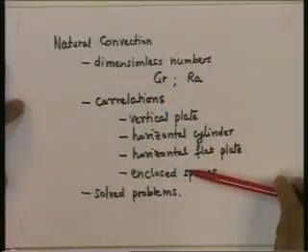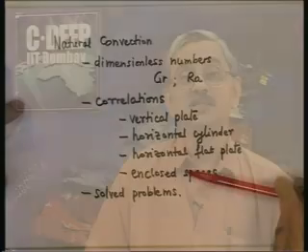So, whenever you solve a problem in natural convection, in any situation, use the proper natural convection correlation, obtain the natural convection heat transfer, but simultaneously also compute or estimate the amount of heat transfer by radiation, because in natural convection that will play an important role. Thank you very much.